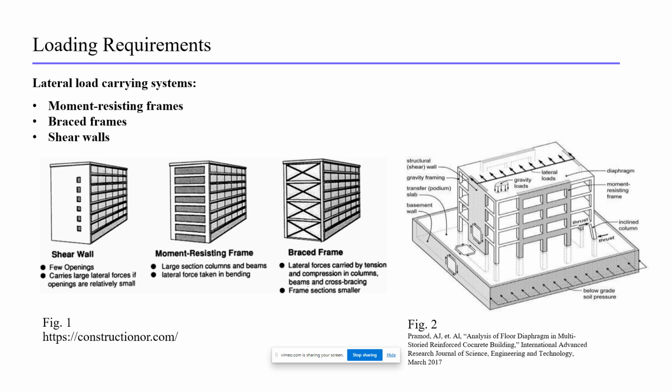these systems, the bracing systems, for example, you need to have a stiff diaphragm. That's shown in Figure 2. What that is in a building is usually a stiff floor, a concrete floor on a deck, or something similar to that. You need that diaphragm to be rigid in its own plane. So the analogy with a platform is the relatively thick plywood or aluminum, which is attached to a frame that takes that lateral load down through the bracing into the ground. So clearly it's important to take lateral loads into consideration in any case.